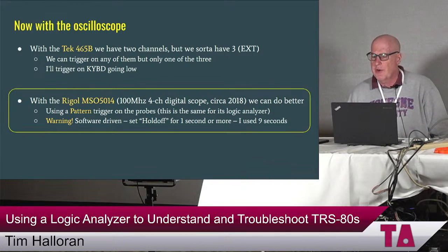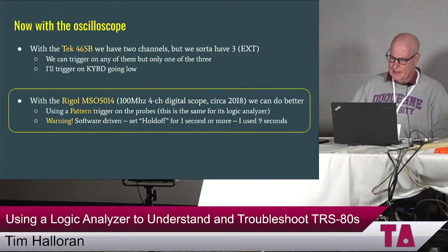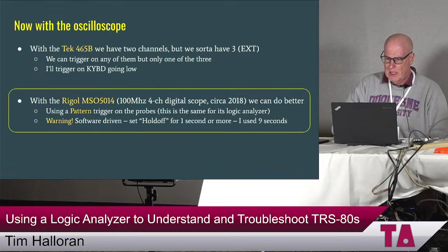This is a little bit tricky to do with the logic probes. It has a software-driven hold-off, and I had to play with that. I used a very long time, 9 seconds, to get this to work, but that's kind of whatever your modern scope has. It might work, it might not.